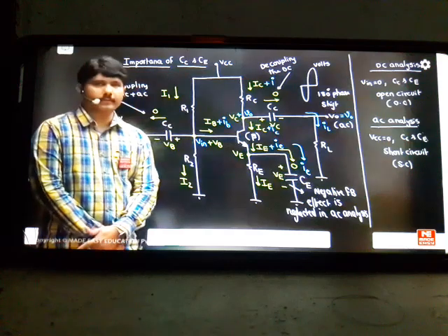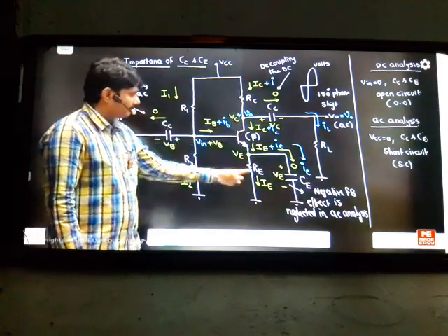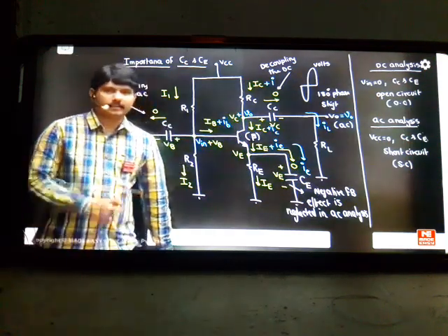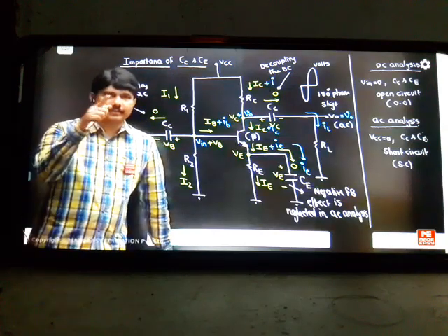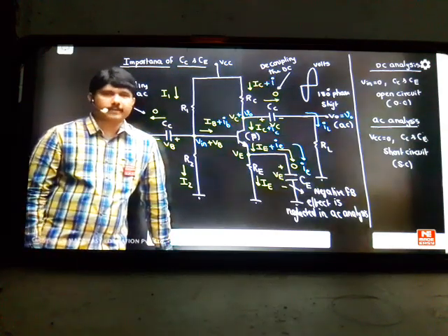Vishal, DC current, where will it go? What's the question here? This whole is DC current, right? DC current is going from top to bottom. Where will it go? It is clearly written on the board. It is going from VCC to ground. The DC currents are flowing because capacitors cannot accept the DC current. Only the blue color lines are AC currents. The capacitors are accepting those.